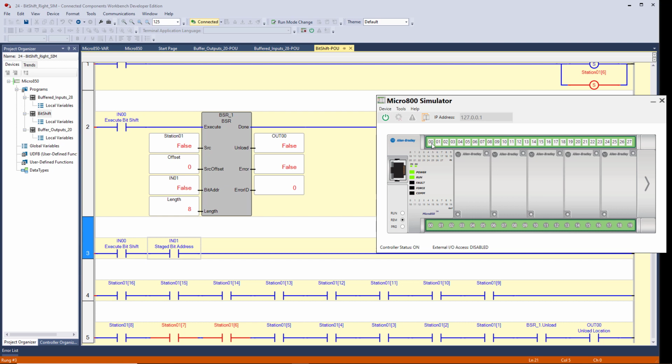And this is going to do this all the way down the trail. Now, if I happen to turn on input 1 somewhere in there, shift it, turn input 1 back off, now I have another bit in here. And as I keep shifting, you see that bit pattern of those length of 8 bits keep shifting to the right every time I go on and off with 0.